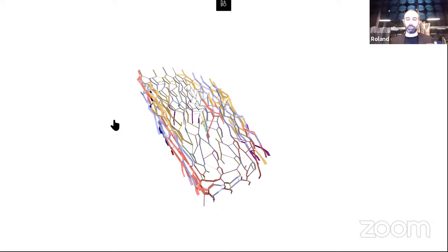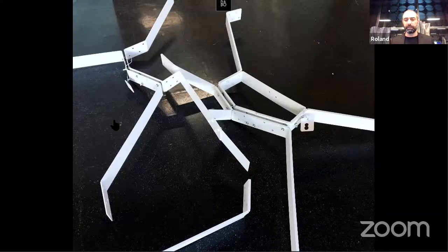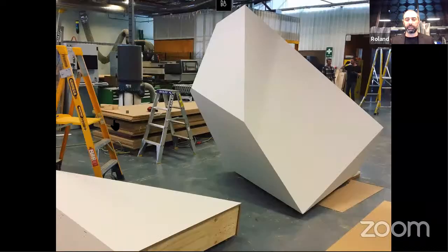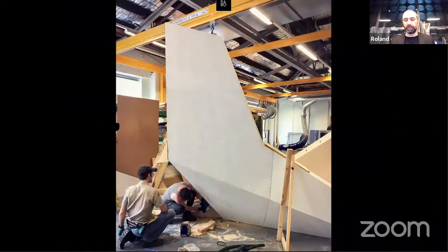So we had to rely on more traditional means, in this case, a folded steel structure. These were laser cut pieces of steel, which were CNC brake press folded to create the agent body structure. And these sit on top of a more conventionally produced base. The base is fabricated from timber using 5-axis and 3-axis milling techniques.